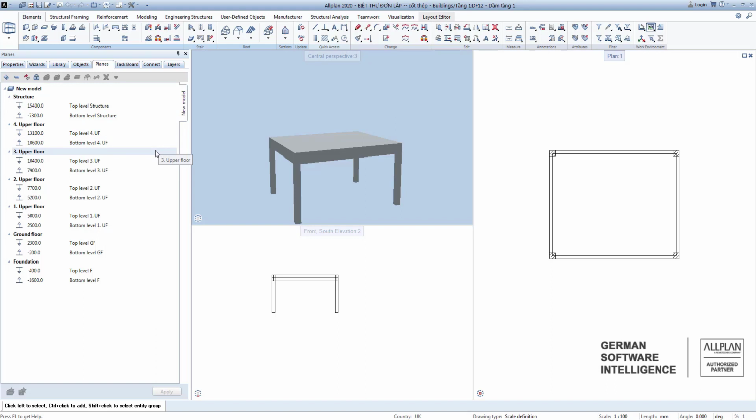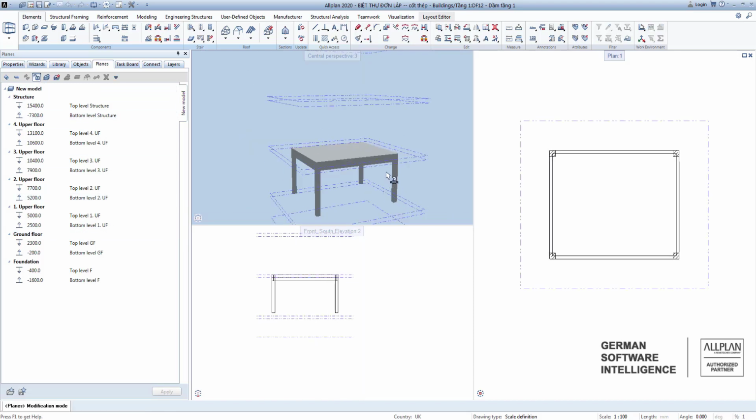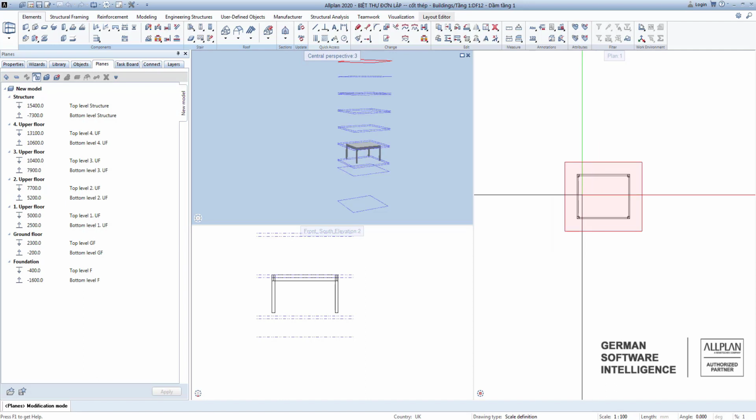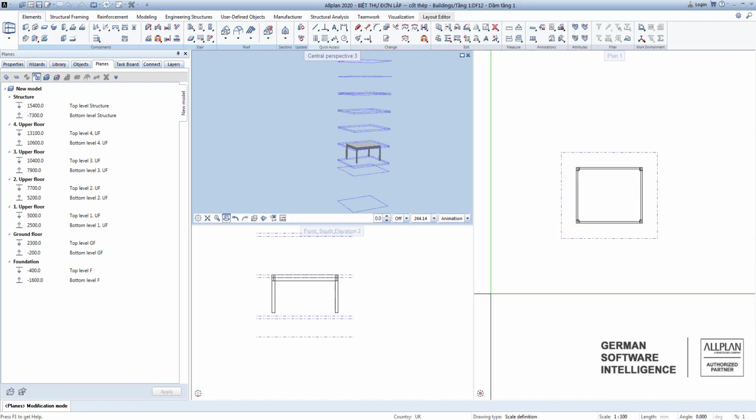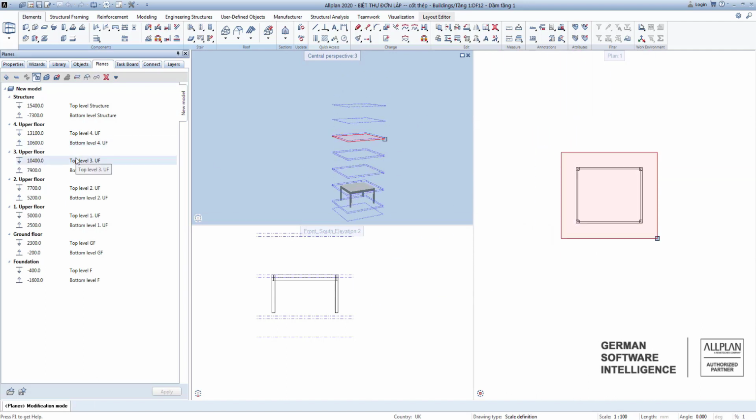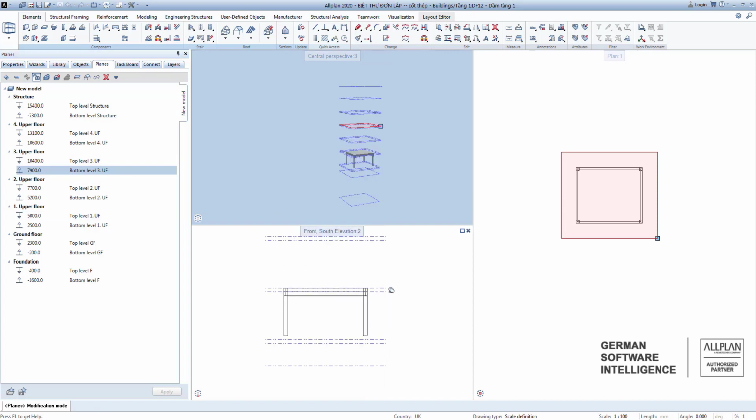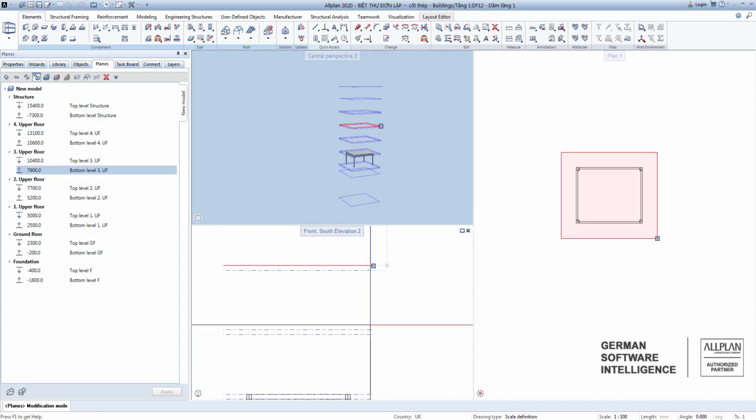It is especially important when there are many objects at the same height, which we will usually see in slabs, walls, columns, etc. You can show these planes by clicking on this unlock symbol. The planes will appear in the viewports visually. The components of our project will later be in the range of bottom planes to top planes of each floor, like this.